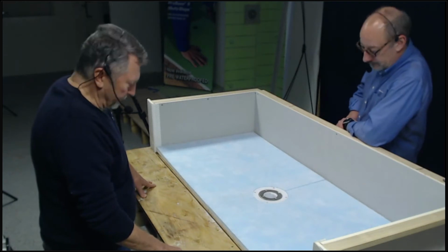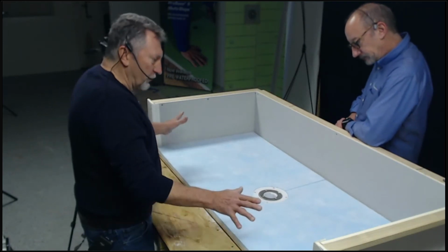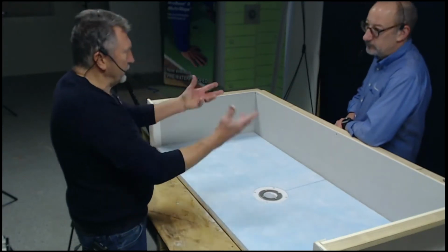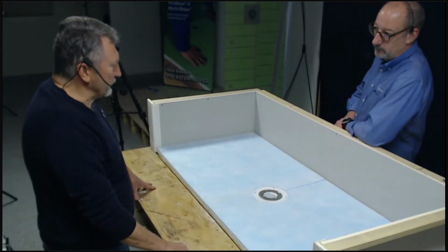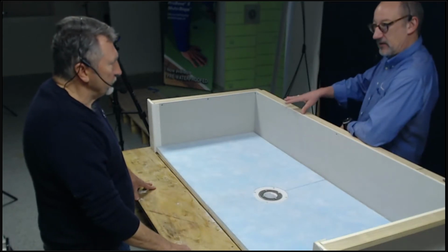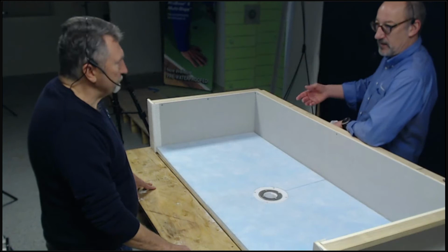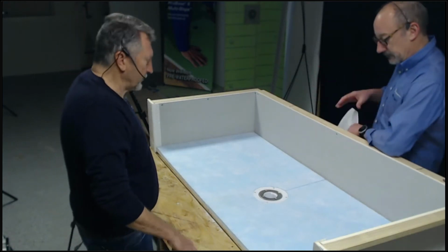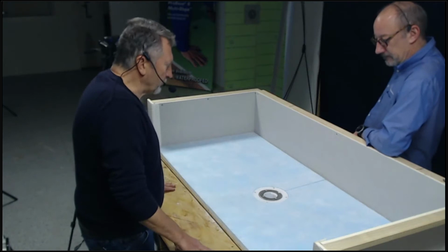That's correct. Now that I've confirmed that my fit is ready to go, I'll bond that down with my modified thin set. We'll show how to do that in our next segment, but you would basically bond it down with a latex thin set, back-buttering to the side like you would large format tiles. Step it in. Pretty straightforward. And then that's ready for the waterproofing on the top of that.